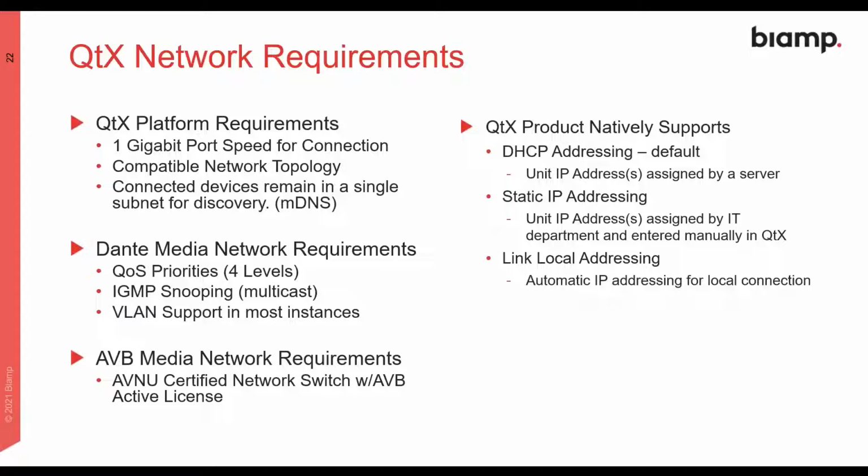So again, going back to what I was mentioning about planning ahead for the topology as needed for AVB or Dante. If you had a Dante system, that doesn't require the specific AVB license to run on the Dante switch. There might be other things that you need to set up for the multicast to be supported, but it might not be as finicky as far as getting a specific switch for a device.